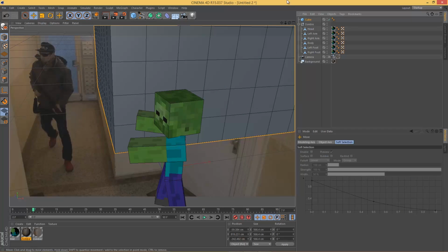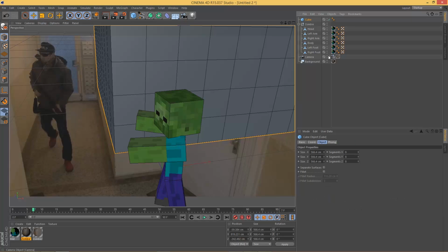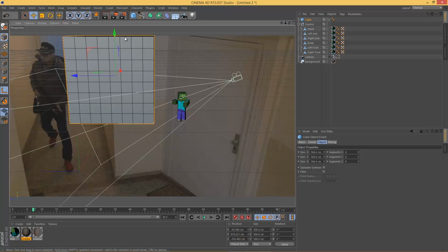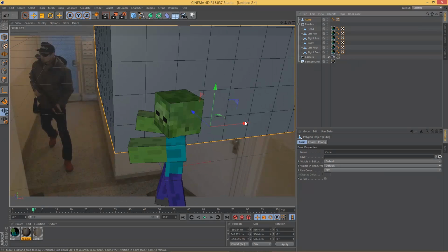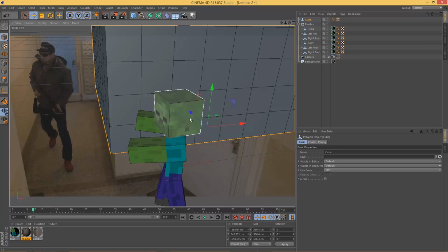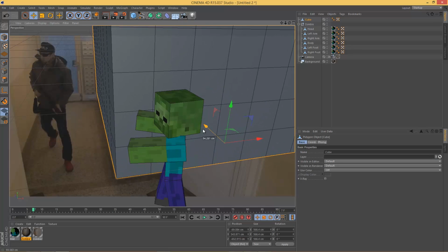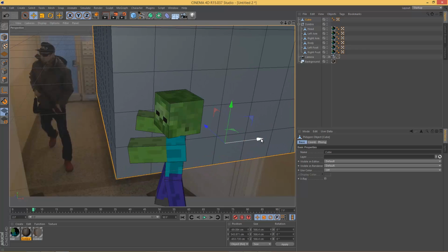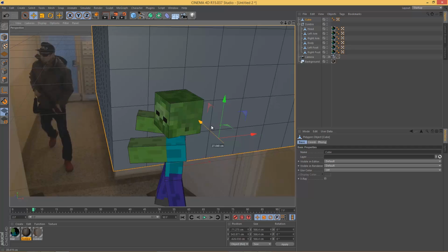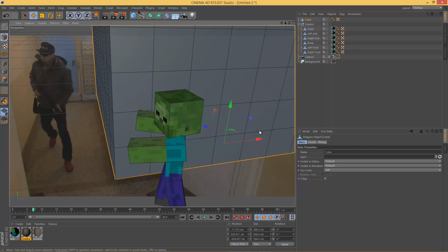But now you have to adjust the X and Z position again. So we'll go back to the editor camera and move it. At this point, you should not change the Y position. And what I'm doing here, I'm just changing the axis with the L key, and then hit the L key again to move that object, and then move it forward a little more, again to hit that guide point, and then you're good with this one.